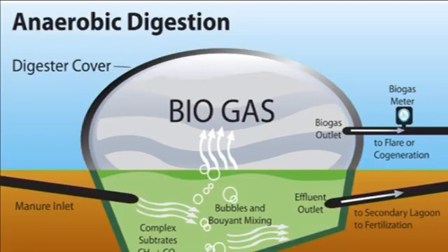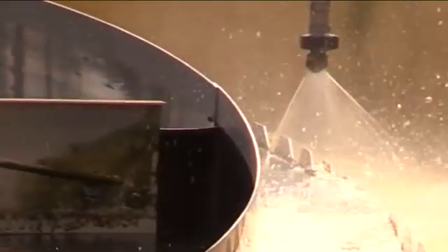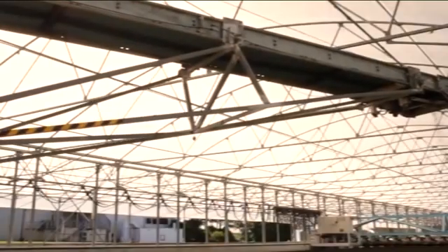In addition, anaerobic processes enable biogas production, with associated energy recovery, and are also characterized by low sludge production. Typical yields are less than 0.1 kg volatile solids per kilogram of COD removed.